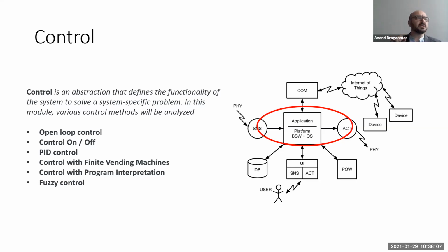When we are putting some money into the vending machine, you'll see, even you'll feel the changing of the state. First of all, I'm in the state of acquiring the money. After that, we are checking the money. After that, we are providing information: please check the product. Waiting for the selection. Yeah. After that, when it's selected, provide, open the door, close the door, and go to idle state. This is control with finite state machine.